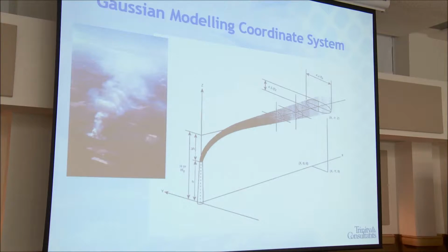So the long story short is that if I was to take a line and bisect any of that diagram, any of that plume, we would have conservation of mass at each location. If we were to get into more complex Lagrangian models like CALPUFF, that actually might change with time. But that's one of the overarching simplified assumptions that we have when looking at the AERMOD model.